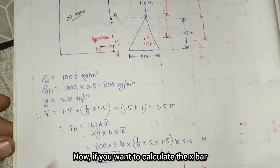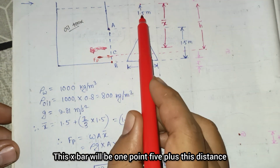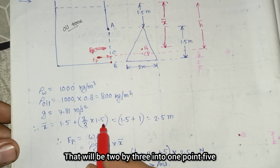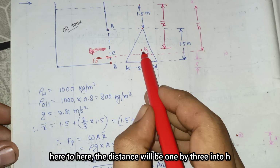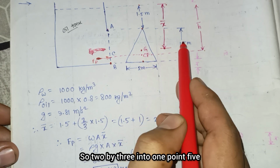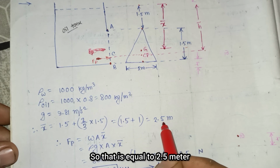Now if you want to calculate this x bar, it will be 1.5 plus this distance. What will be this distance? That will be 2 by 3 into 1.5. From here to here the distance will be 1 by 3 into h, and here it is 2 by 3 into h. So 2 by 3 into 1.5 is 1. So x bar is equal to 1.5 plus 1, so that is equal to 2 meter.